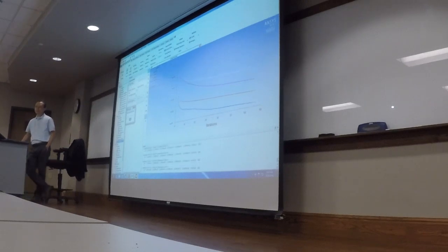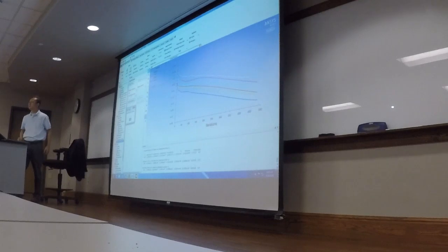This time, so let's remember, for 1 kg per second, it's 95 to 5. Here, let's reduce that to 0.1 kg per second. Just from our intuition, 95 will go up or down. Down. Super. It's going slowly, so the water will have more time to go to the branch.